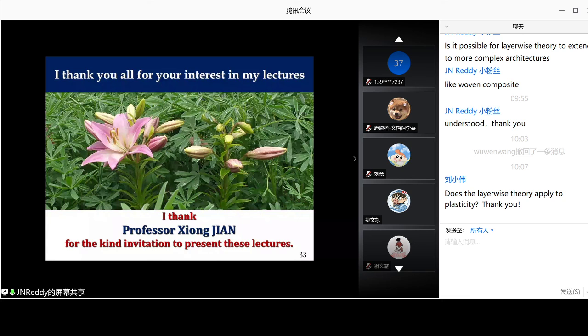The bending of beams: the plasticity grows from the top and bottom toward the center, because the stress is large at the outset. So you have to subdivide through the thickness. That means you divide the height of the beam into layers. So the layer-wise theory is much more suitable in those cases, because you can assign which layers, which elements in the layup, are already plastic. So it is definitely a better approach.